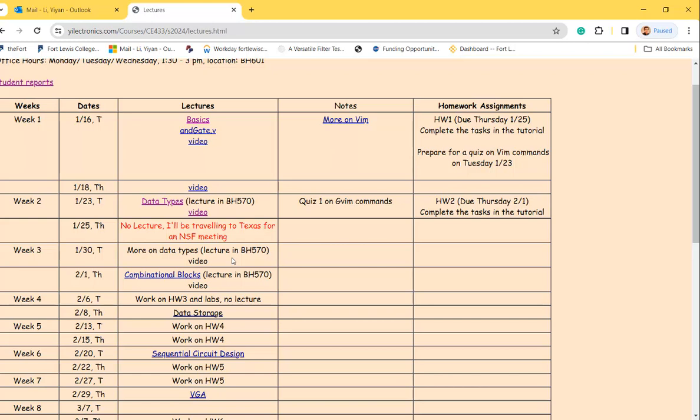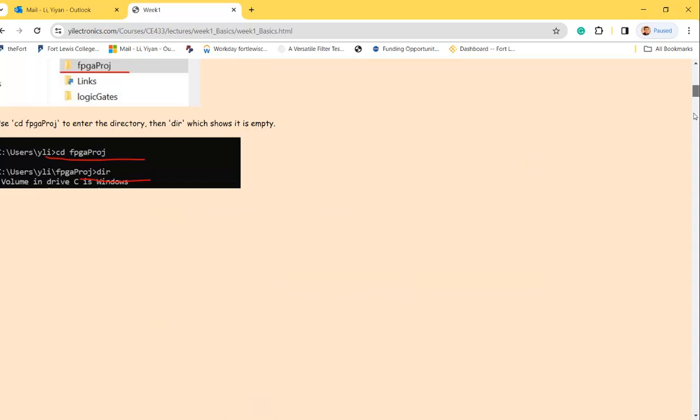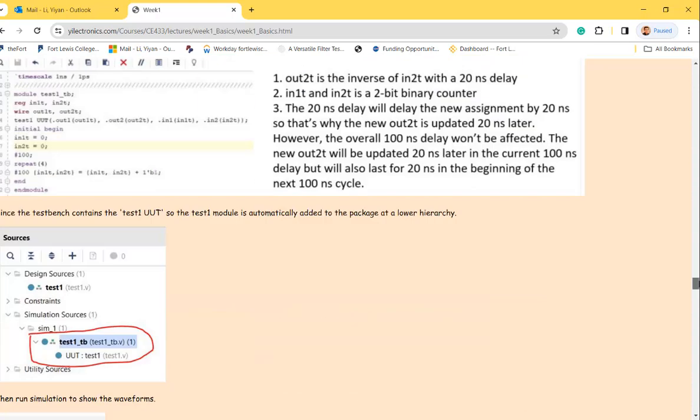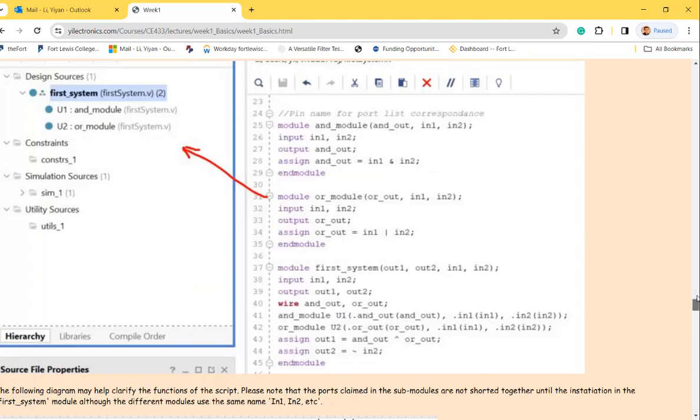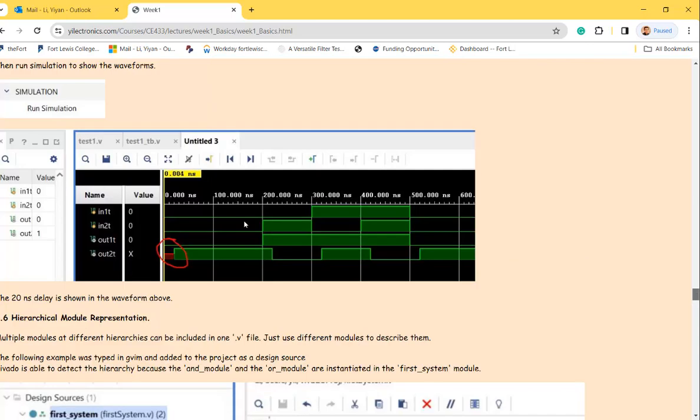And there's another example for the non-blocking and blocking. If you just run the simulation, I won't be able to tell what's going on, right? The results are being combined into a data bus, so it's not showing every single bit. And just by looking at the simulation, you won't be able to tell which bit is showing which data.